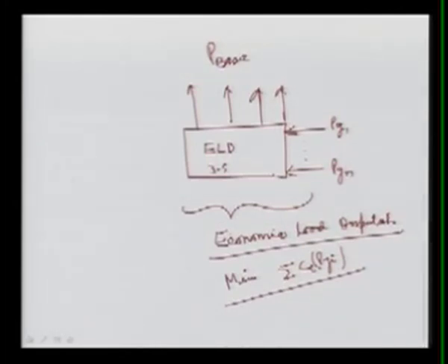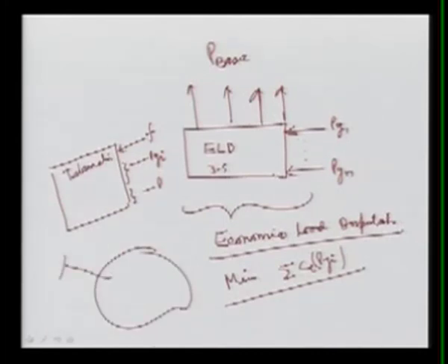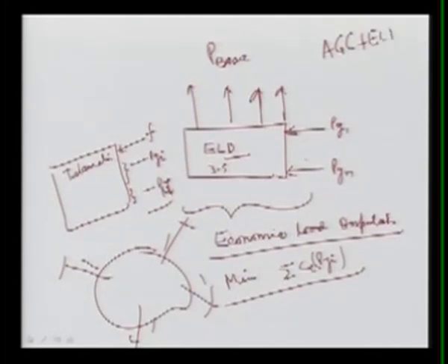So what we did, we had another unit that is called the telemetry. In telemetry we are measuring the system frequency, that is only one input. We are measuring here the power, that is the PGi of all the generating units, and we are measuring here the tie lines that are going from that area. Means this is your area, we may have different tie lines here. So how much net schedule, that means we can measure this, this, this, and this, and then we can decide I1 from area i to 1, and then we are processing here and we are doing this whole logic. So if you are combining this with ELD, then it is called your AGC included with your economic load dispatch, here combined logic.